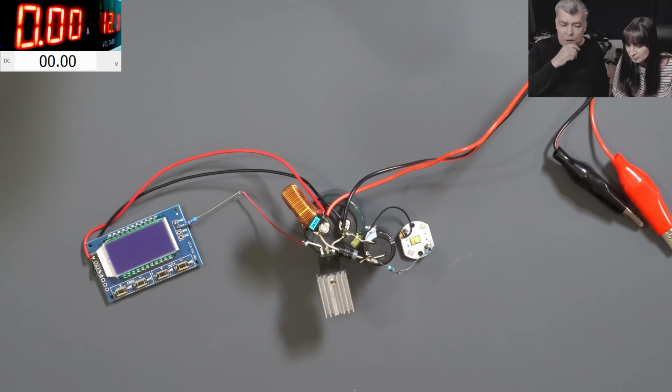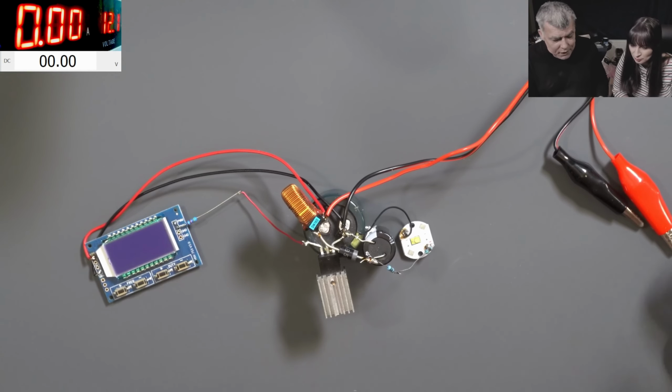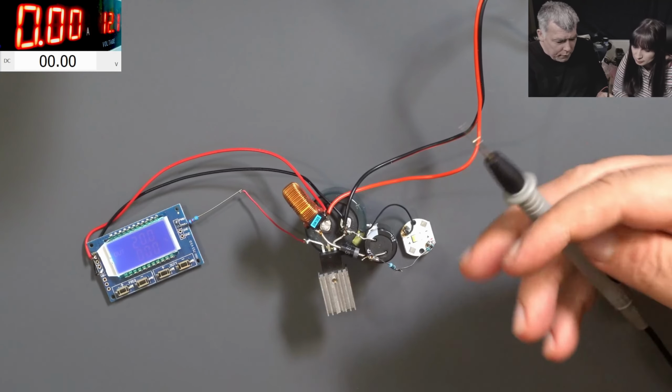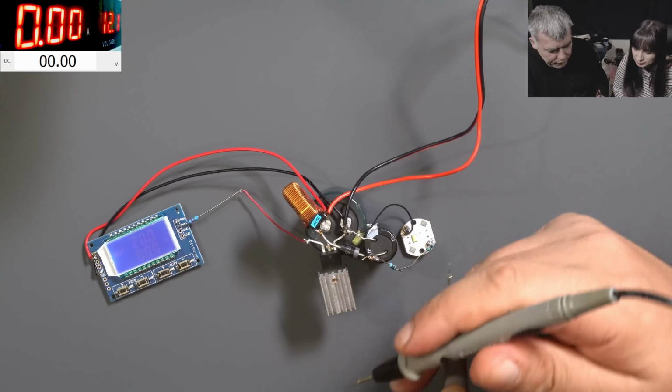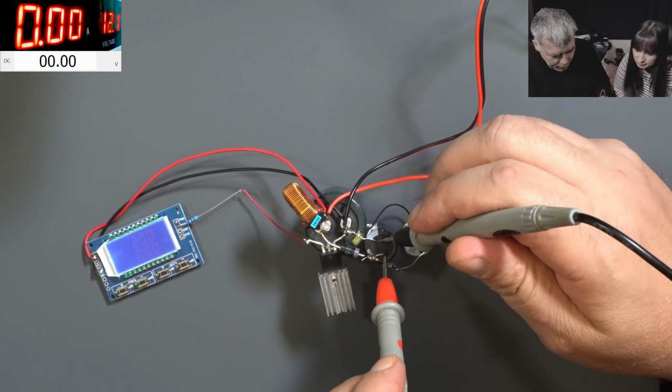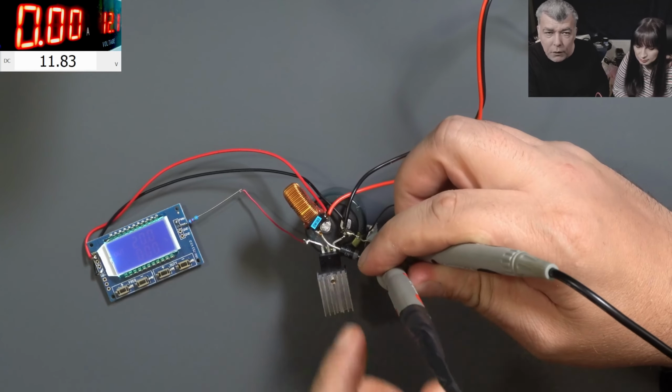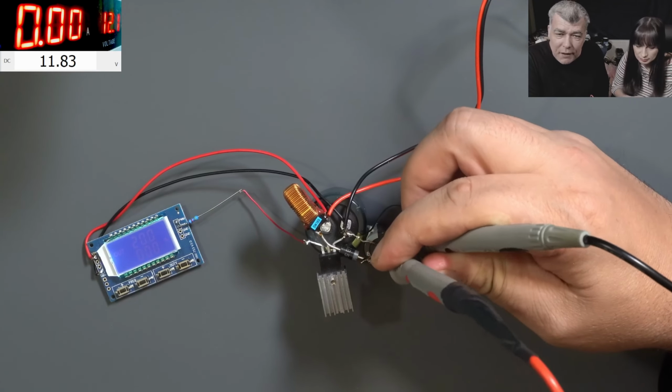You remember last time we checked it was like 400 milliamps and 30 volts, 30 something? 33, I think. Yeah, let's check now, just to understand what optimization means, yeah? Good. So I will hold here and you follow the voltage on the screen, yeah? Minus, plus. I want you to follow the voltage and increase the duty cycle.